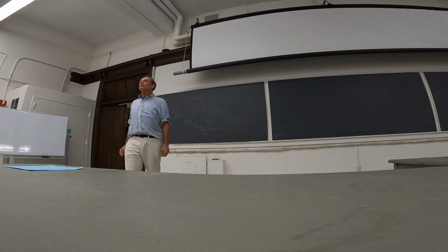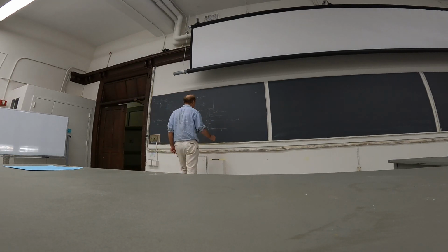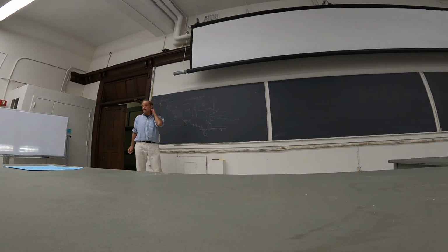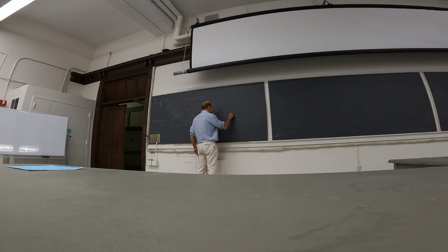Now, if I have too simple a feedback control, and we'll see this a little bit later, then the output could look something like this. That is, the output could adjust, but it may never go back to the desired value if this is too simple feedback, and it gives me what we call an offset.